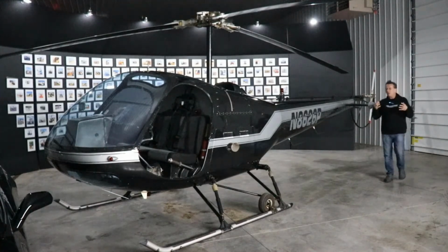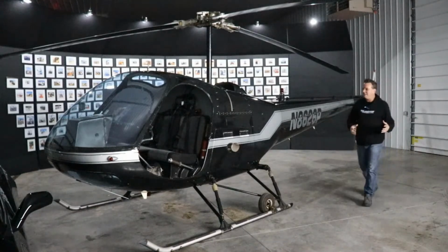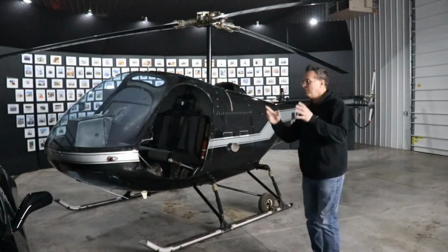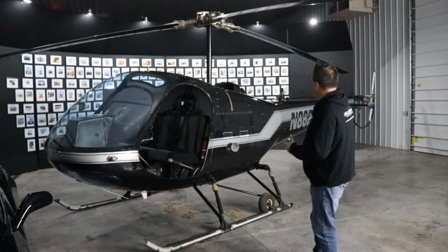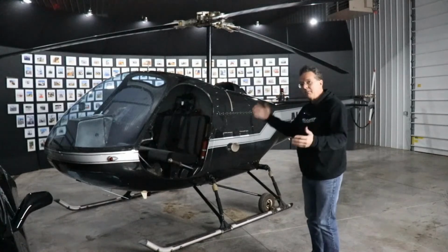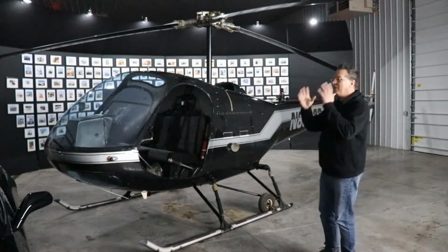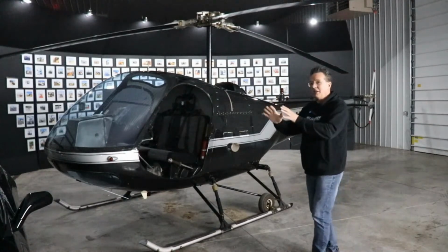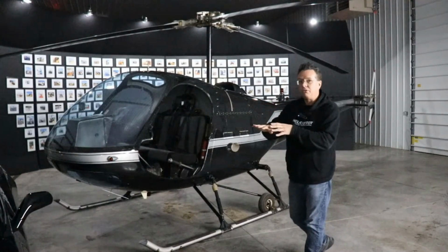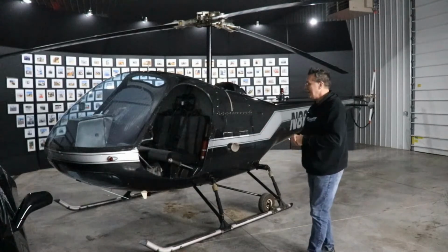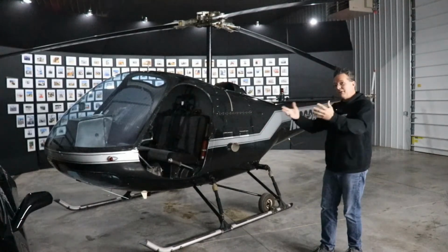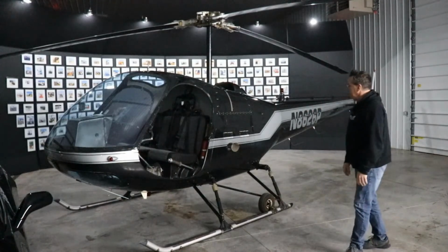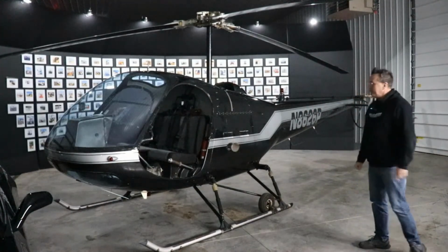So when you hear the term helicopter streamlining, there's not much to it. That's why in forward flight, you can actually have a tail rotor failure, the tail rotor drive shaft could break, the tail rotor could fly off, and you're still going to be able to keep flying pretty straight. You can continue to fly until you can find a good place to do an autorotation landing. And you can do that because you've got that airflow going down past the sides of the helicopter. That's helicopter streamlining.